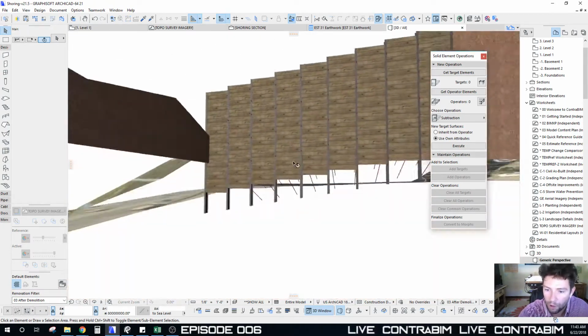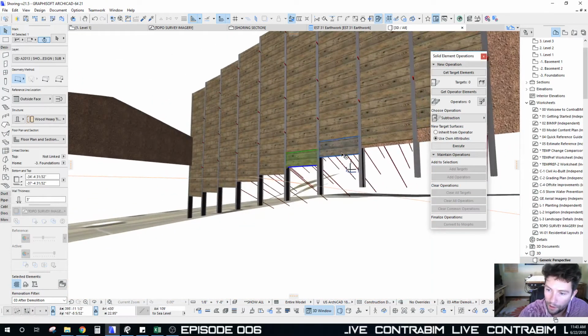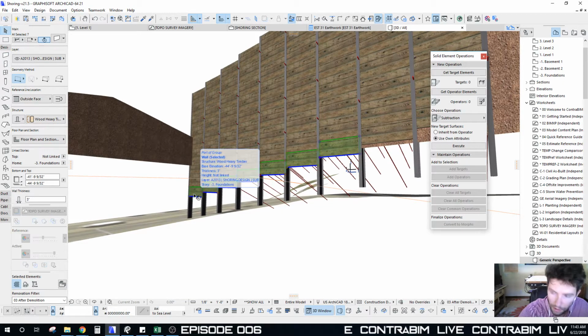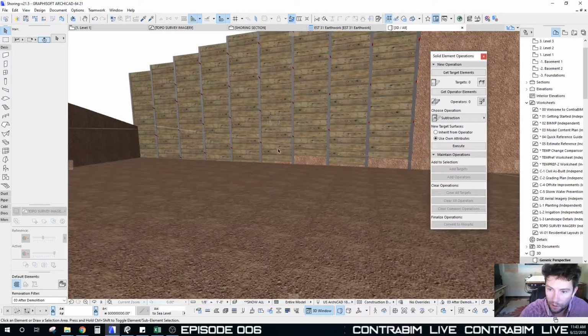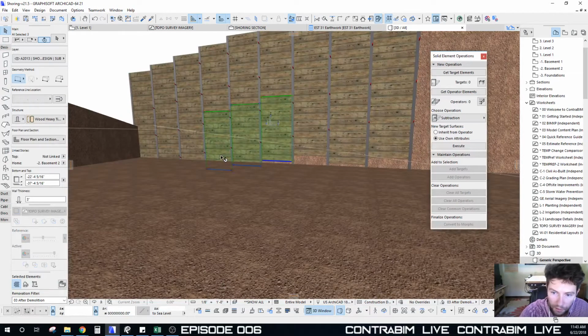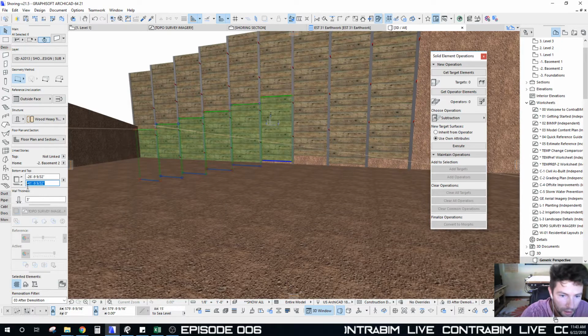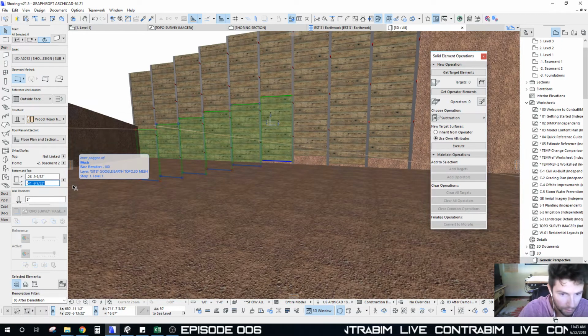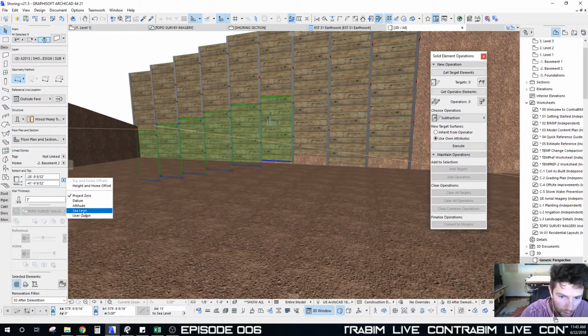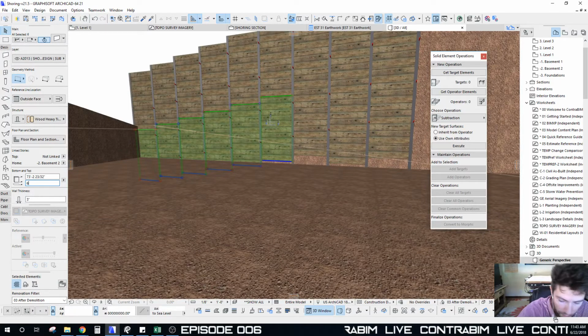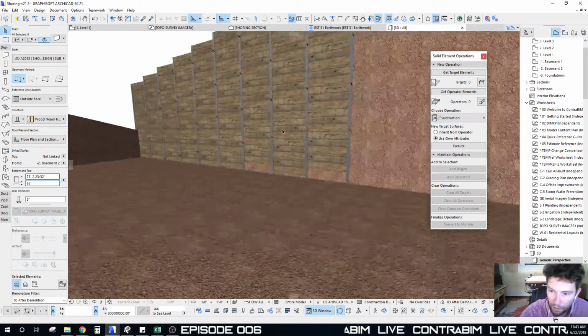So that's working. All these down here, these extra layers, I'm going to go ahead and just delete those. And then the rest of these here, for all of that, I'm going to just set the top of these to, let's just go to our sea level. And I think 65 is where the bottom of our excavation is.